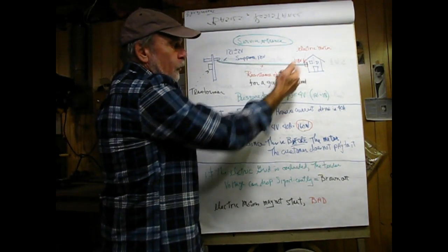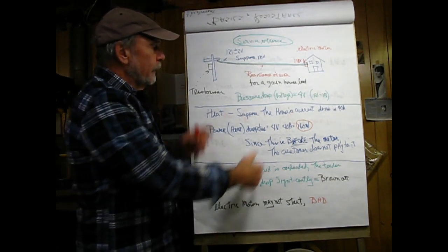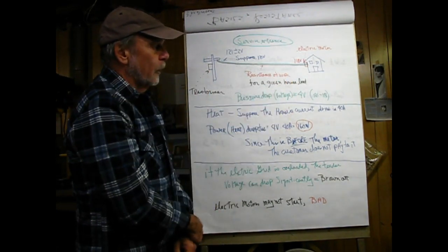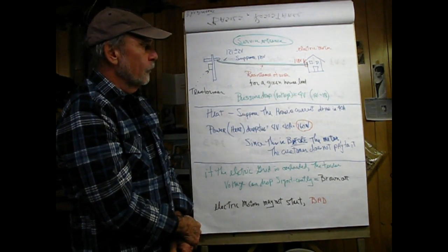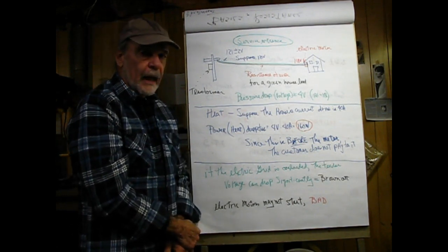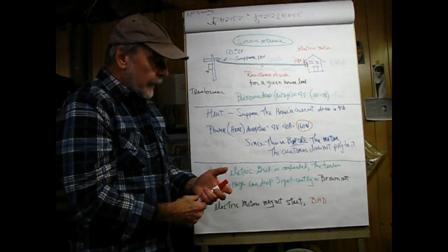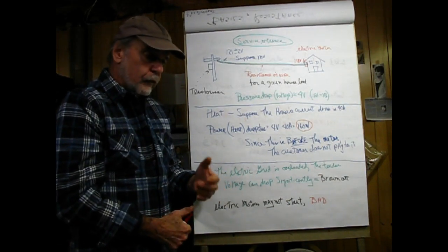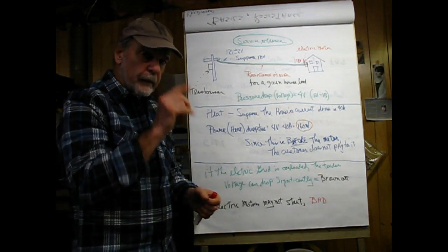And the house is drawing some current, don't know what, but the voltage drop in the service line is producing a voltage at the output of 118 volts. And what we can see from that, again, is we have a 4-volt drop in the wire for the service entrance. Now, if you have a furnace or perhaps an electric water tank, you may note when it turns on you'll see your lights take a dip.